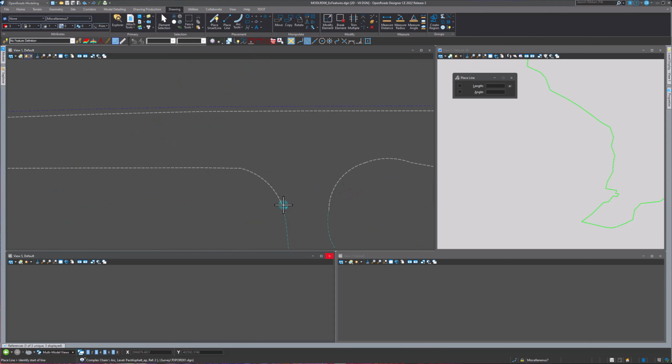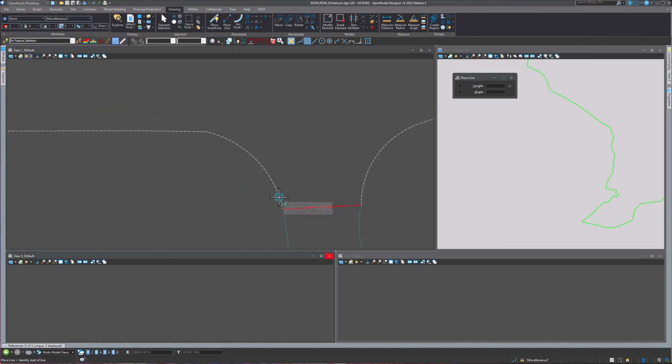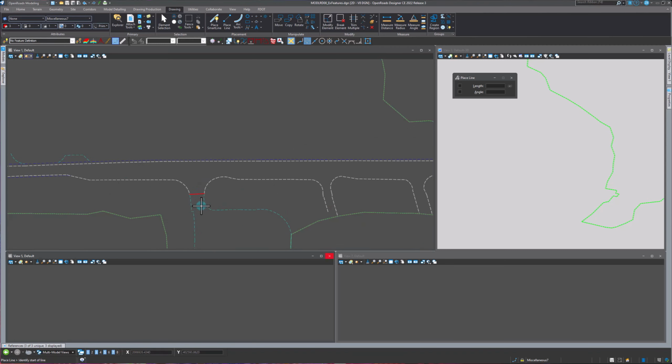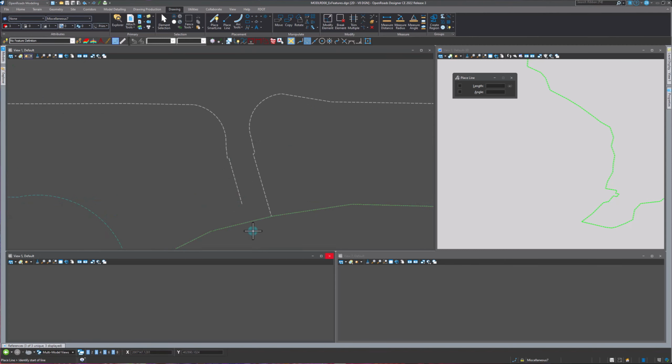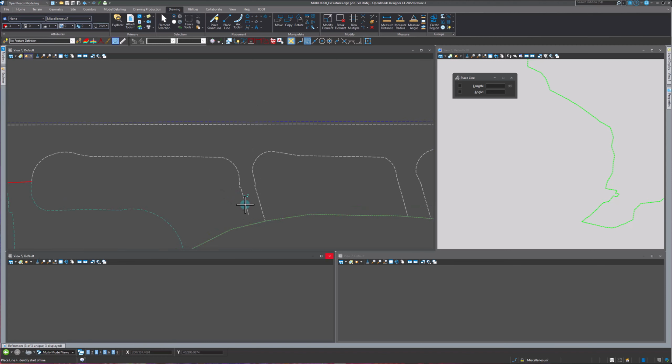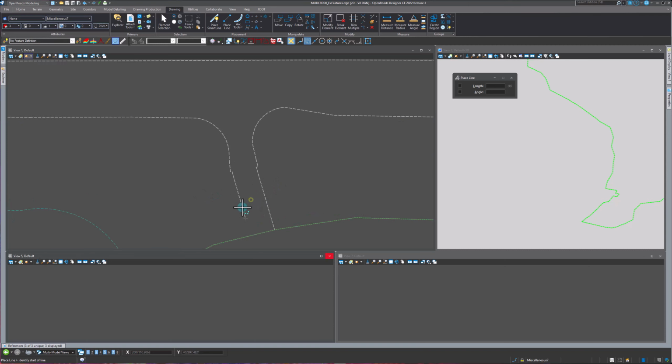And so we'll continue kind of closing these off. So you can see, like, I'm just closing this off where the pavement asphalt ends and this driveway begins. So that, to me, is signifying some sort of change in the pavement. And then here you can see, like, I don't have a line that keeps going here, but typically we're not going to be constructing this far out. So all I'll do is just grab here to that endpoint, the shortest endpoint, and use my snap to go perpendicular to the line across from it. Close that off. And we'll do the same thing over here.